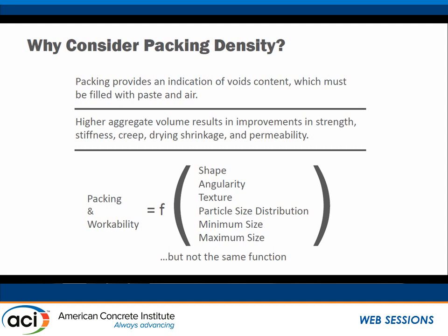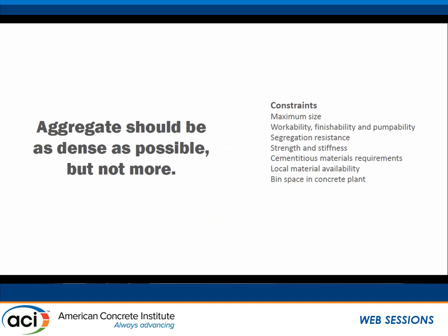So when we talk about the aggregate, optimal packing is not necessarily the same as for workability. And so if you look at what packing is optimal, really we can say that aggregate should be as dense as possible, but not more so.